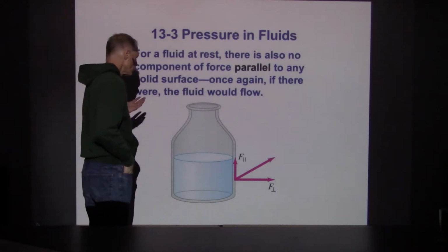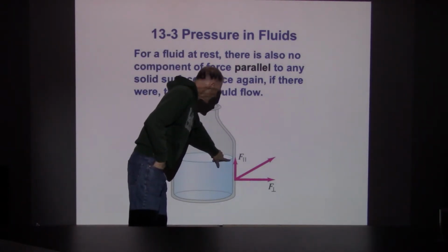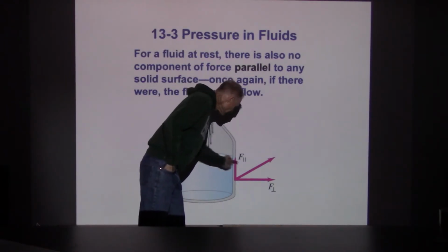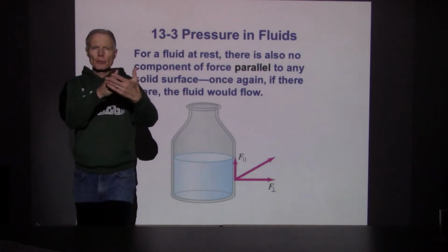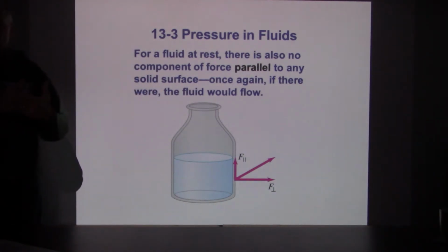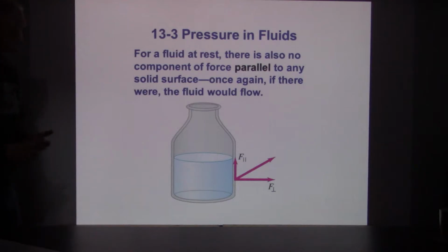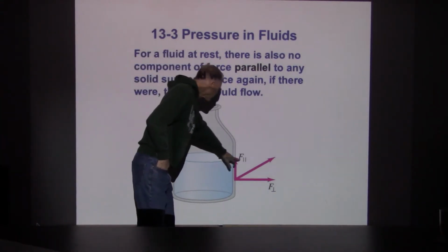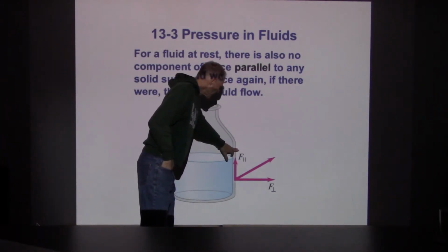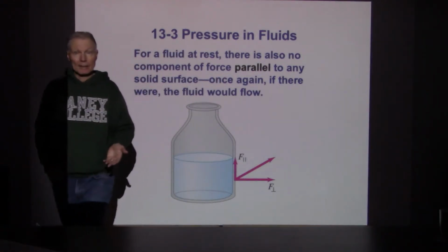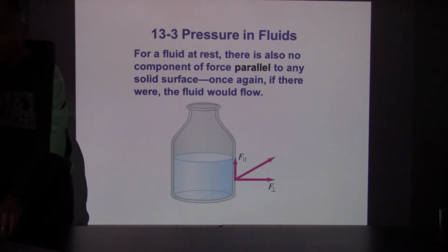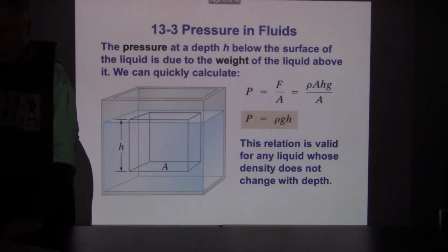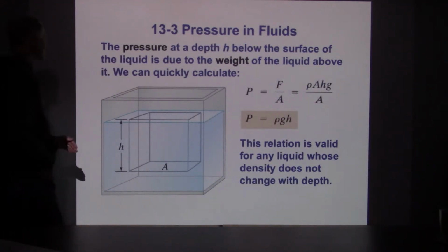Another issue going on here is the size of the container. The fluid is going to exert a force. The force that it exerts is perpendicular to the surface. It's perpendicular because the molecules are in random motion, and if there were a sideways component to that, then the fluid would not be static. So the argument here is because the fluid is static, the force that it exerts on the walls of the container is perpendicular. All right, let's take a look at pressure increase.